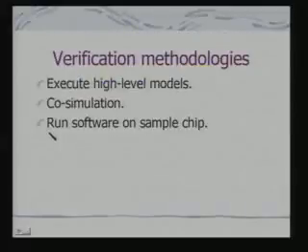And then you do a verification: execute high level models, do co-simulation, run software on a sample chip, and finally check whether it is working or not. Co-simulation means simulation of both hardware and software. In fact, all these platforms provide you with a development environment where you can do a co-simulation to check your design.